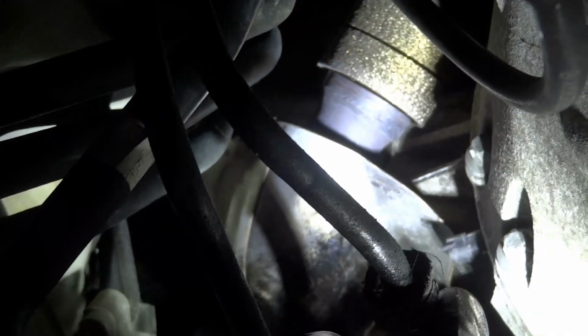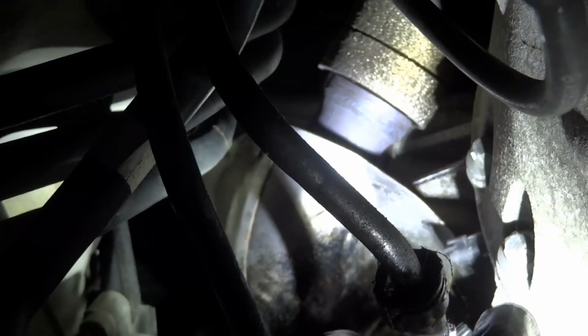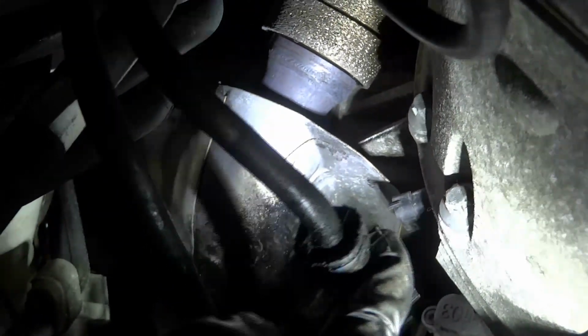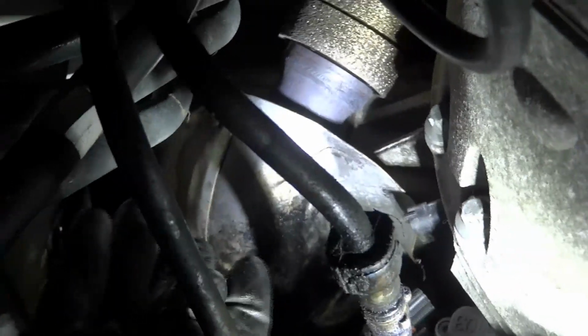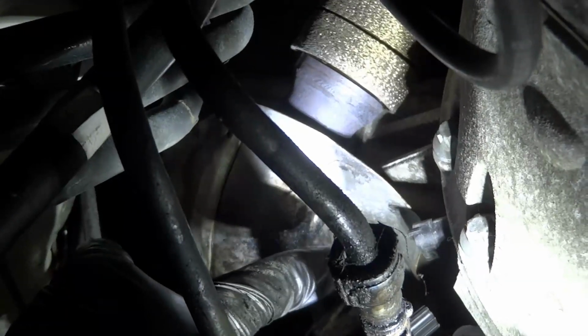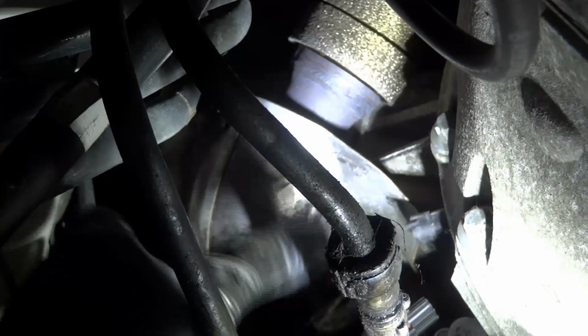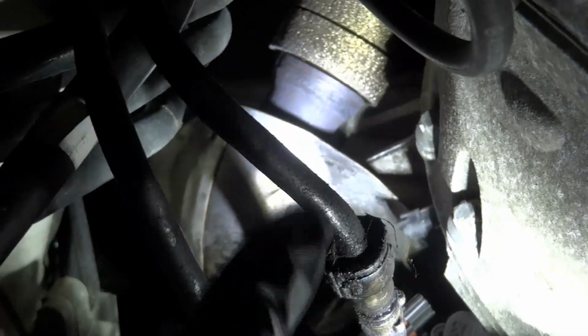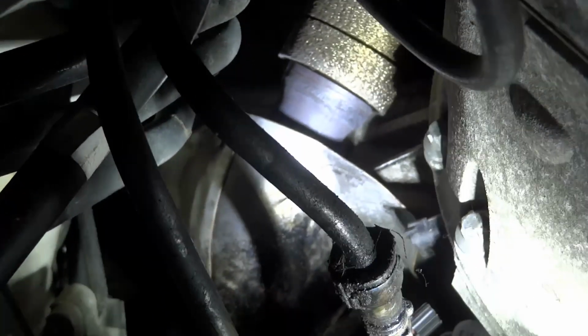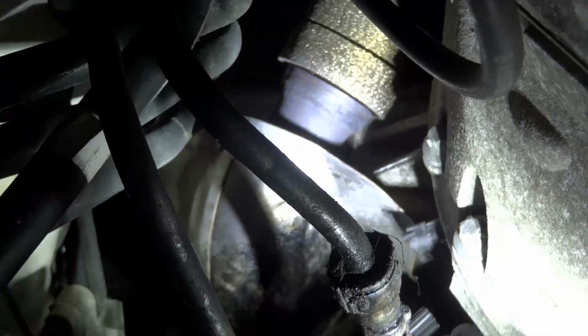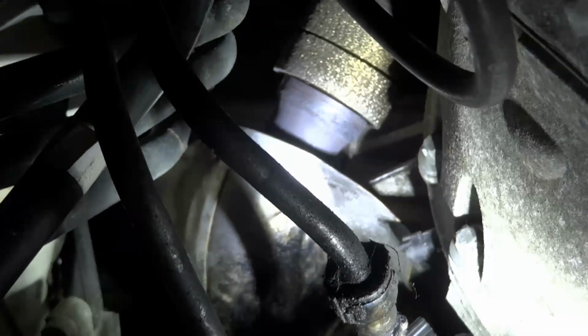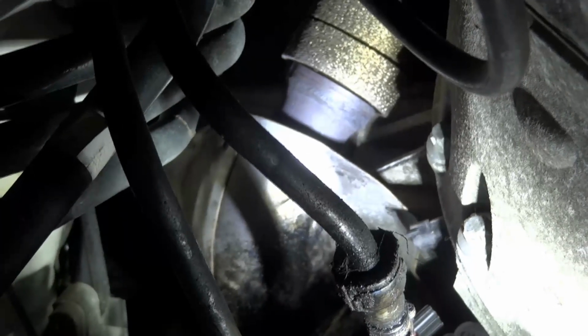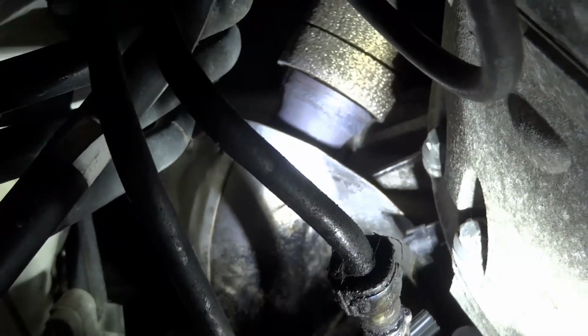I'll bring you guys back up once I get the sensor out and after I inspect the trigger wheel, because I can't really bring you guys up there to show you. I'm just gonna have to put a mirror up there against the exhaust manifold and have someone bump the key so I can see if the trigger wheel will be moving as the engine is spinning. Okay, so you're just gonna have to take my word for it, whatever results I'm gonna get, and then we'll go from there. So I'm gonna remove the sensor.